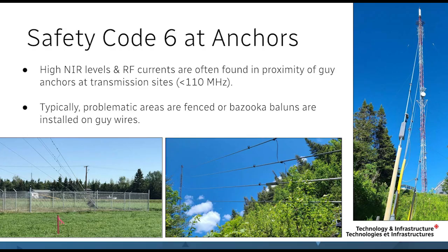In the last few years, we've developed a bazooka balun method that we can attach to the guy, and this creates a high impedance on the guy wires. It stops the current above the ground, and at the ground level you have much less radiation, and it makes your site compliant. That's really nice. However, you have to find out that there's a problem in the first place by measuring that you're overexposed, and you have to get to the site, and you have to incur some expenses to get there. So you don't know for sure that a site will be overexposed. You just have to measure, well, that until now. Well, maybe not now, but in the near future.